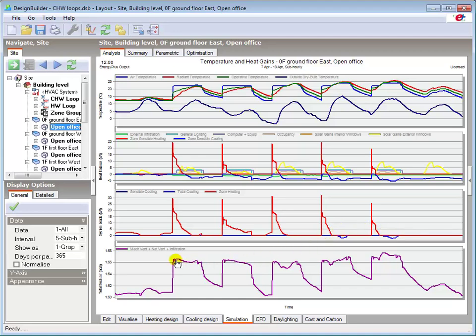Although the fan coil unit is scheduled on at a constant fresh airflow rate, the total fresh air graph appears to show variable airflow rates. Checking the scale on the y-axis, you can see that the variation is actually quite small and is a result of changes in the relative density of internal and external air as the temperatures change in time.